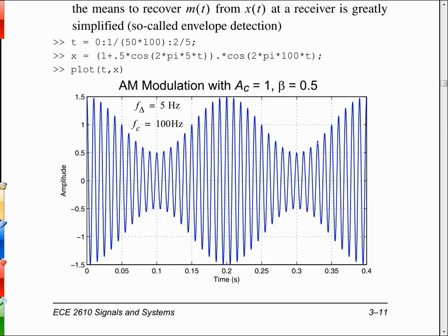If I plotted this with 850 kilohertz in a MATLAB plot, what would we see? It'd just be solid blue shaded in there, because there would be so many cycles in there. It'd just all be hazed in with a bluish color. We'd have to zoom way in on it to see the individual cycles. In this case, the message signal is only at 5 hertz.